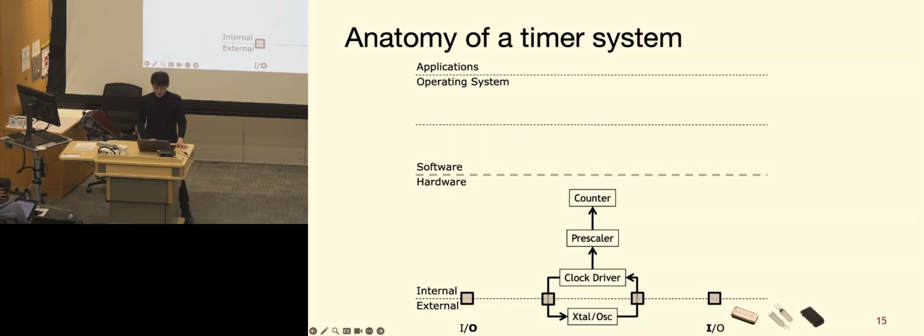And then we have the counter registers. It does very simple things, but it does them very well. Basically, it increments or decrements or both at each of the clock pulses. And we typically use this to measure the duration of time, like how long the program has run, or to keep track of what your periodic interrupt state is at the moment.